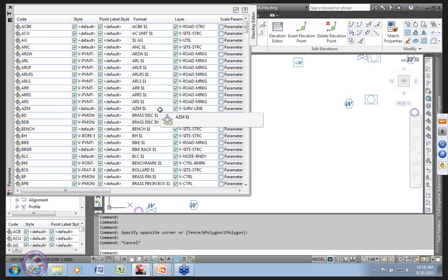And if you import this into a raw drawing from a Civil 3D project, it will actually attempt to make styles that emulate a little bit of what your description keys are. So that's still possible to do. It's still buried away in Civil 3D, and it still works.